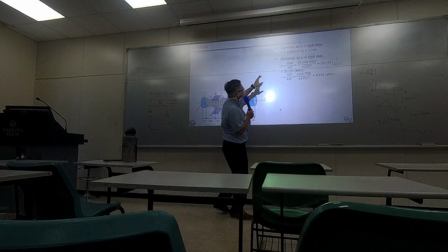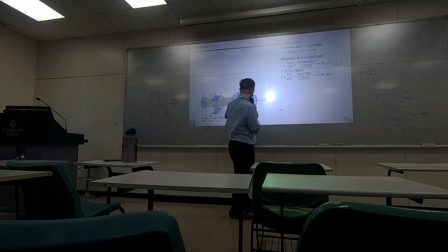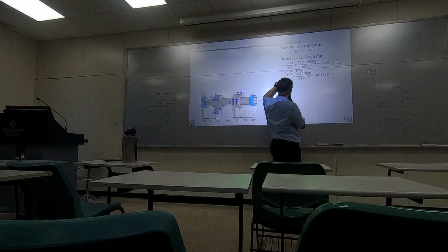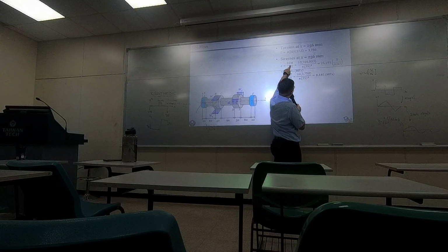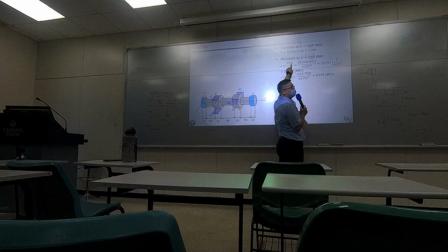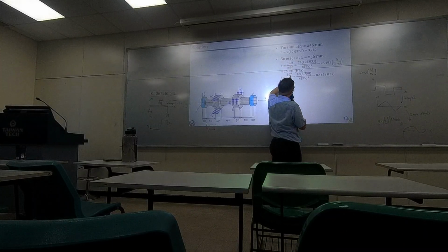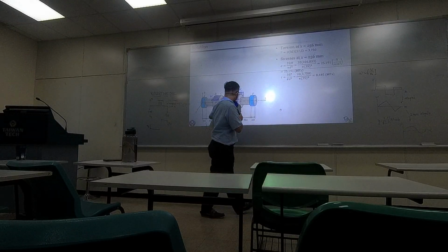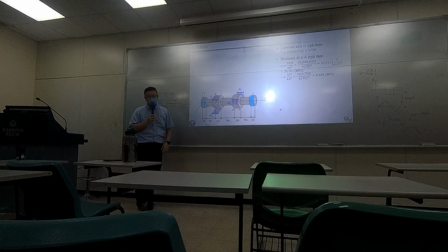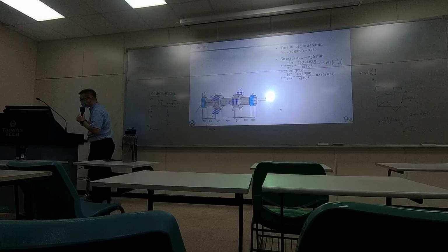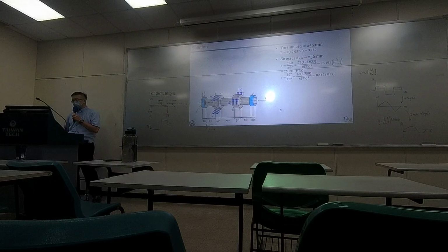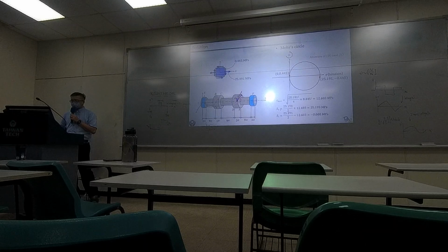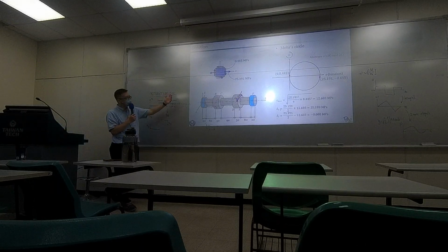So we can now study that critical point and use the stress equation and the shear stress equation, with M being the M total from the previous slide and torque being the value you computed. So you figure out that on the surface of the beam, there is a position carrying the largest sigma and tau. So it will be somewhere, maybe here.